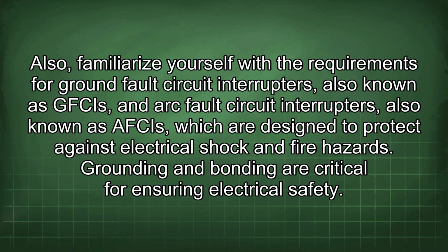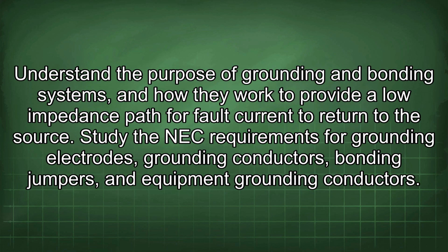Grounding and bonding are critical for ensuring electrical safety. Understand the purpose of grounding and bonding systems, and how they work to provide a low impedance path for fault current to return to the source. Study the NEC requirements for grounding electrodes, grounding conductors, bonding jumpers, and equipment grounding conductors.